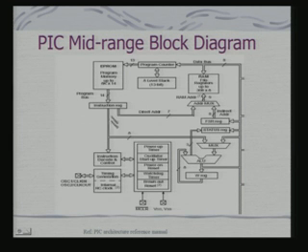Now, there are two kinds of bus structure you have found here. One is the direct address, which goes in through the address multiplexer to select the registers, and here you will find that directly the 8-bit data as part of the instruction is coming to the multiplexer by which it is fed to the ALU. Now, why is this bus there? To enable immediate mode addressing, that is, when the data is part of the instruction.